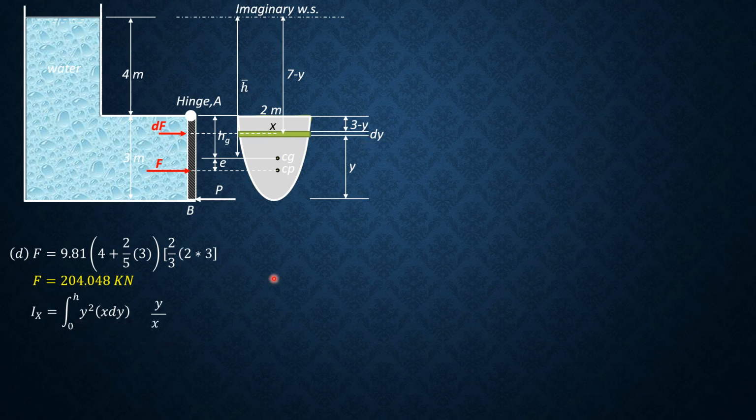Now, by the square property of the parabola, y squared over x squared equals 3 squared over 2 squared, or in general, h squared over b squared. So that means that x is b over square root of h times square root of y. That's the value of x in this integral here. So Ix equals the integral from 0 to h.